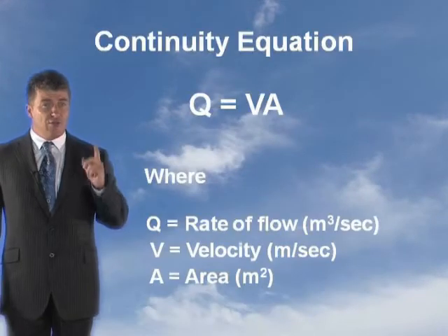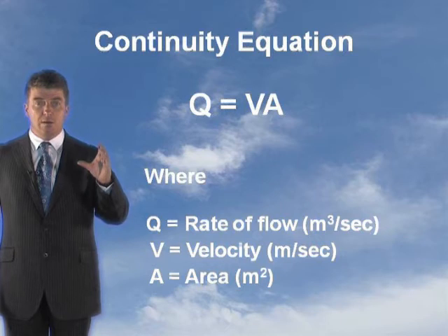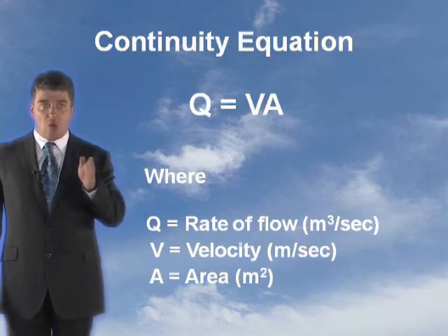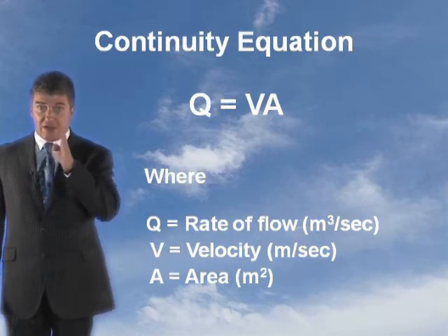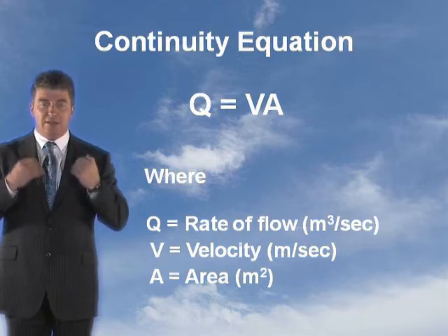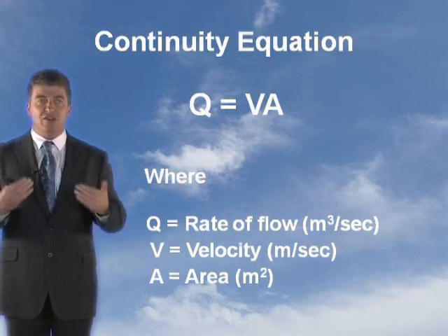Now, before we go through some model answers applying Bernoulli's, you also need to know the continuity equation. When considering Bernoulli's, it's very important to understand this continuity. In a closed system, the rate of flow, Q, quantity of flow, which is always in metres cubed per second, don't forget you've got to get the right format, can be considered as constant.